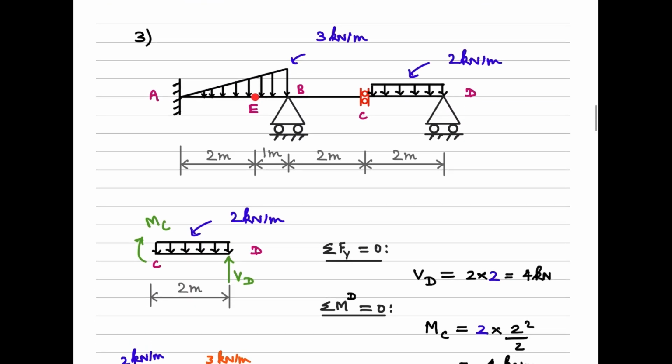So that's it. This last problem we have a moment release here and then a shear release here. So is this beam statically determinate or not? It is statically determinate. Why? Because we have how many reactions here? 2 here plus 1 plus 1. Totally 4 reactions here.